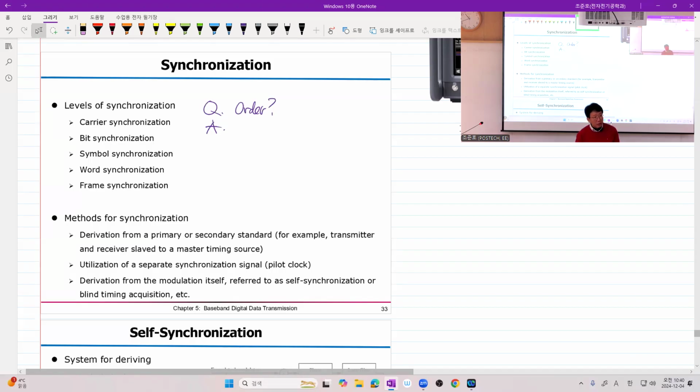We don't know, right? So not only this periodic signal, but also when we transmit, for example, a sequence of -1 or +1, if we transmit a lot and we don't know what the starting point is, even though the signal to noise ratio is very, very high, we may not properly recover our message. So this kind of synchronization between transmitter and receiver, sometimes between receiver and received signal, must be done in digital communications.